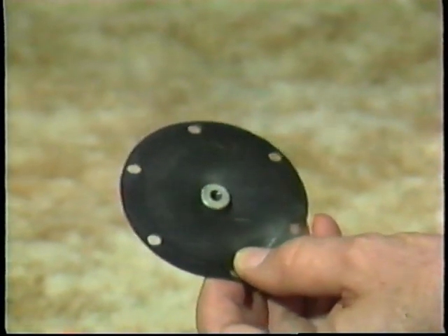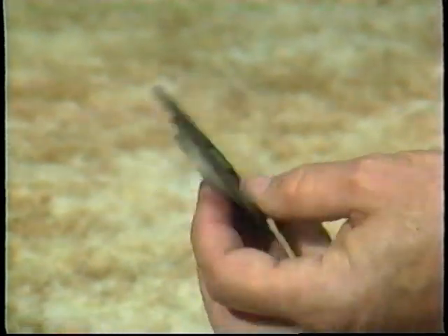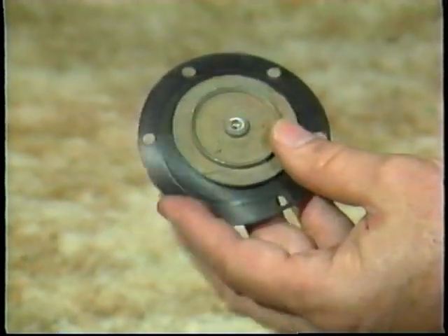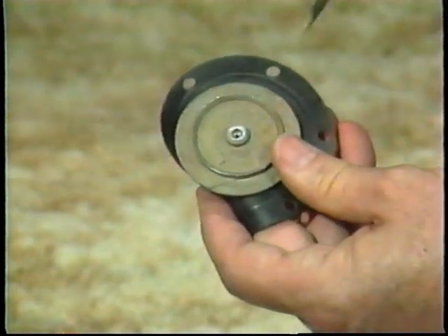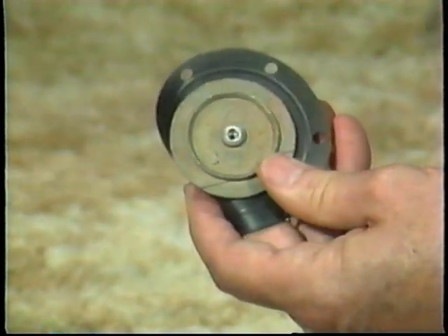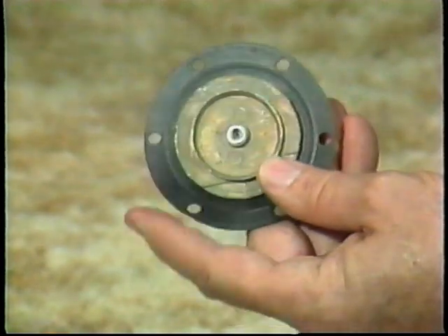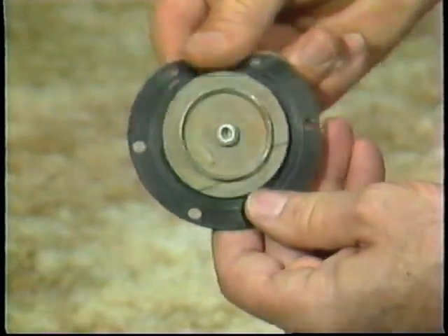Instead of a piston, some venting type regulators use a diaphragm like this. It is usually made from a combination of fabric and rubber, so it is very strong, yet is soft and flexible. It has a small venting hole in the center, here, and the edges flex, so the center of the diaphragm can move up and down easily.